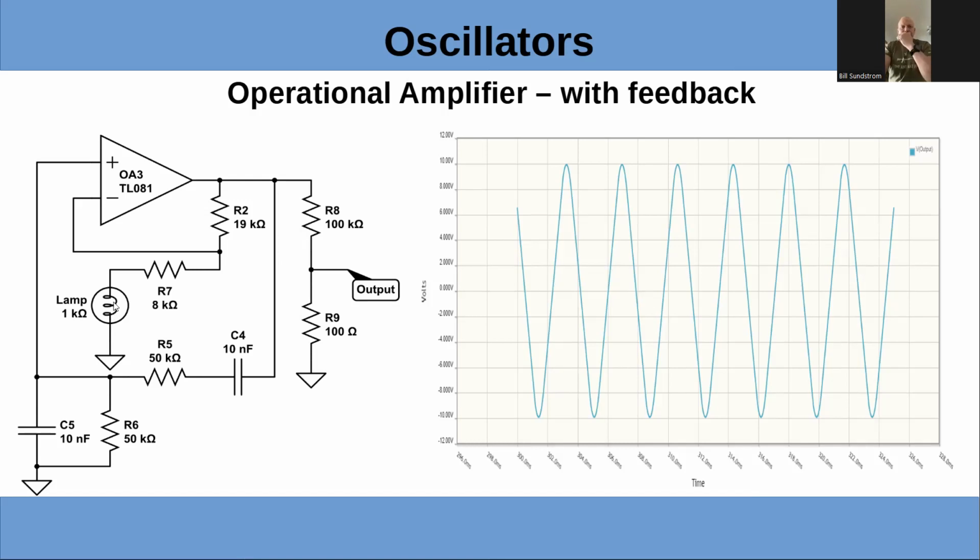Well, these have a variable resistance. They're low resistance when it's cold, just like a normal electric light bulb, and the resistance increases as it heats up. So you've got a variable resistance in there, which allows you to have a variable gain in the circuit. So it can have higher gain when it starts and the right amount of total gain when it is oscillating.